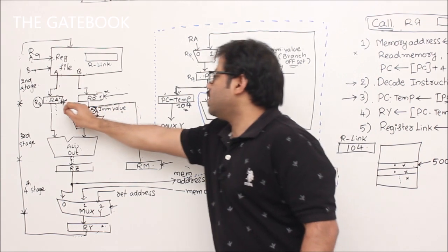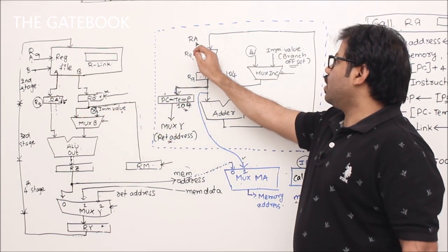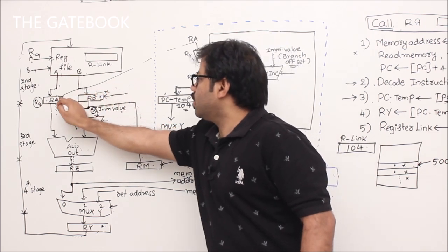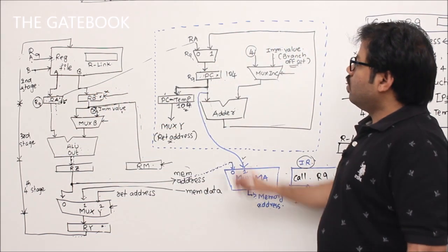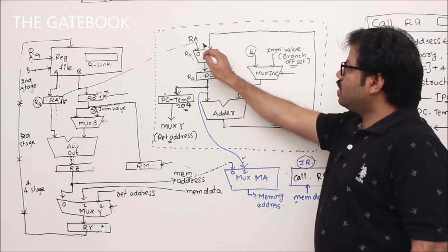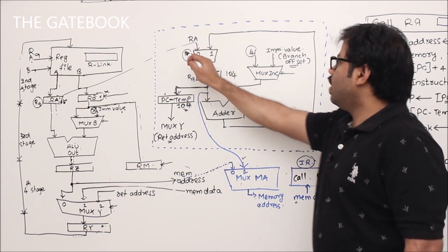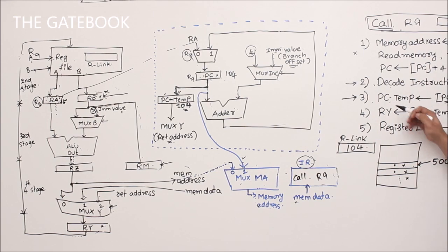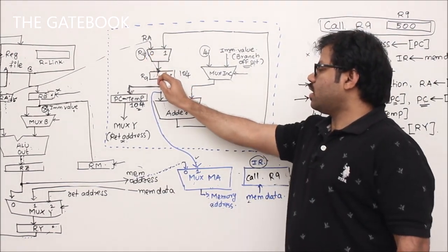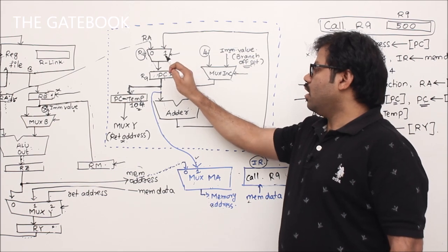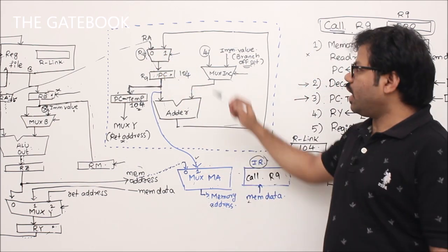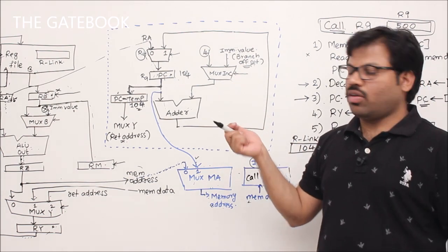This RA, same. Okay. Now here you see. Otherwise, let me show it like this. Actually, it is connected like this. Now, at the third clock cycle, what is going to happen? Since RA contains R9, from the beginning of the third clock cycle to the end of the clock cycle, R9 will slowly flow like this. Assume that this multiplexer is selecting this cable. That is my assumption. Okay, in such a way we can plan it. That is the job of the control circuit.